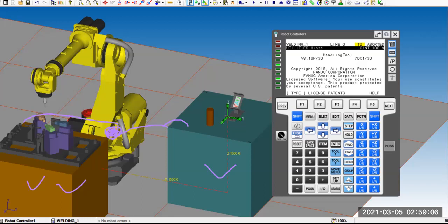So when that work area changes, it's similar to the tool frame, right? One of the advantages of the tool frame is that when the tooling is changed, which I already demoed, for example the length or angle changes, you can just adjust the tool frame. It will save lots of time on the program. You don't need to touch up the positions in the program anymore. You only need to make an adjustment on the tool frame, because your tooling changed. Same idea here.